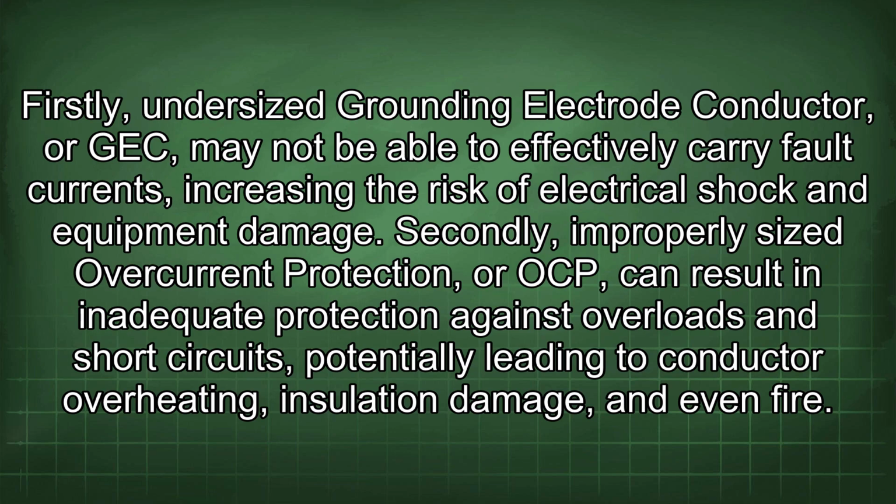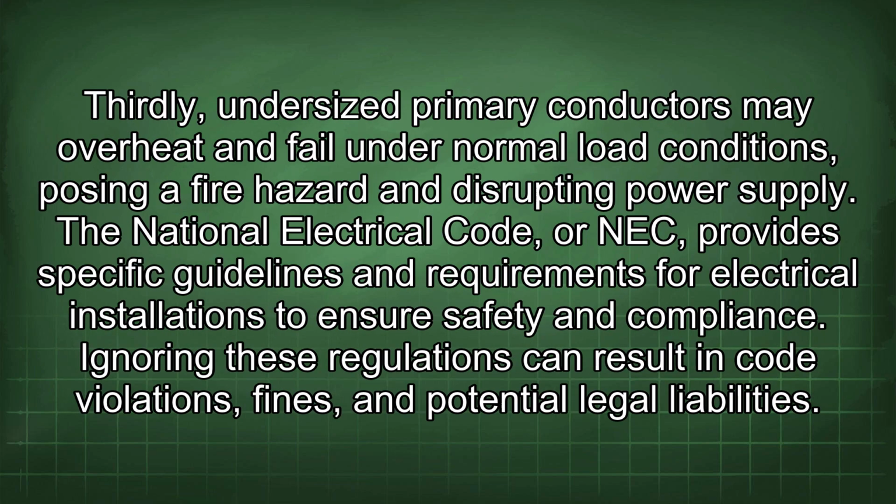Secondly, improperly sized overcurrent protection, or OC, can result in inadequate protection against overloads and short circuits, potentially leading to conductor overheating, insulation damage, and even fire. Thirdly, undersized primary conductors may overheat and fail under normal load conditions, posing a fire hazard and disrupting power supply.